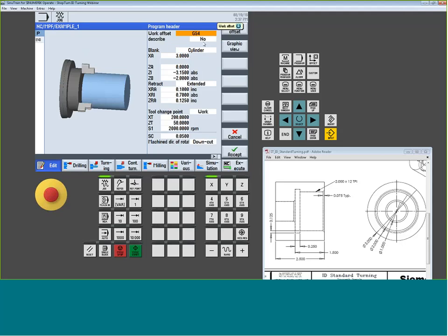Okay, now, commonly in lathes, especially new users on simple lathes, they don't typically use work coordinates. So I've got a couple options here. I can leave the work coordinate selected, whatever one I want to use, but I've got to make sure that there's no numbers there, because it will apply. I could tell it blank. The only downfall of blank is if I leave a work coordinate set up on the machine externally, meaning in the jog screen, and there's a value there, when I run this program, it's going to use that because that's an active offset.